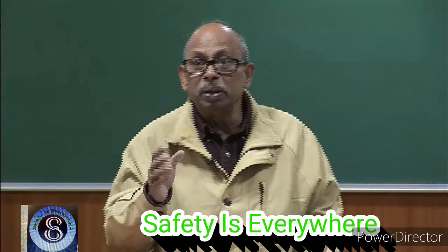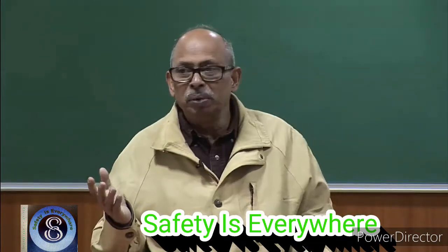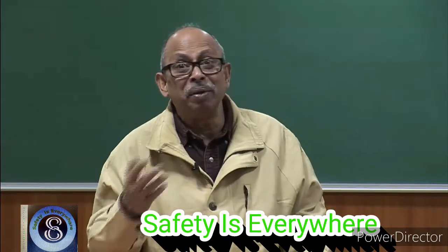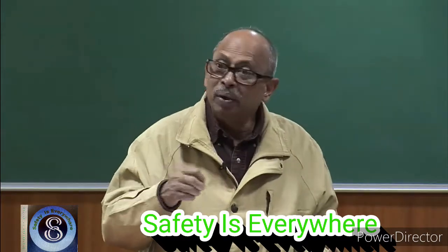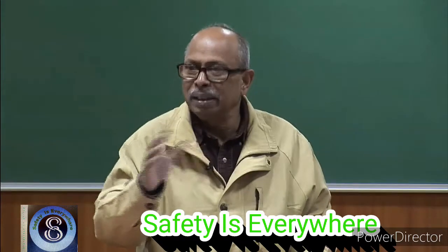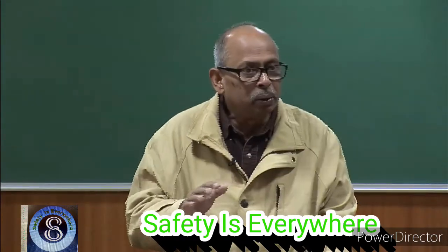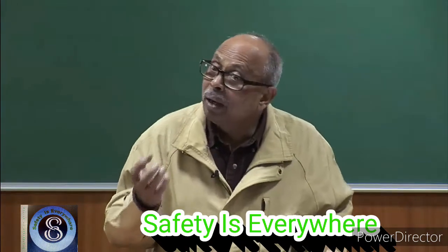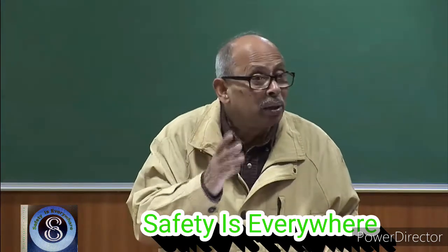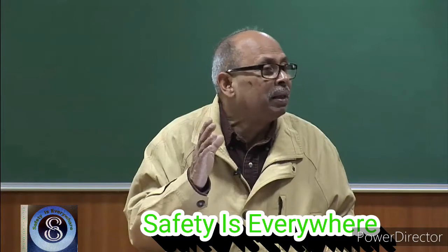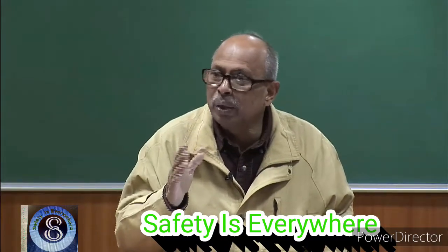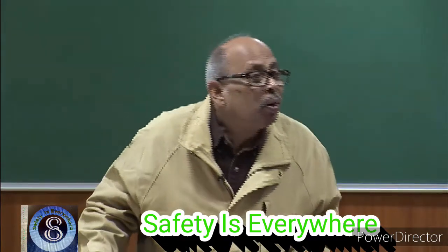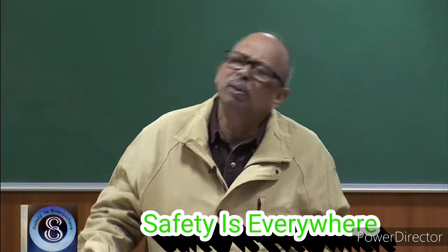Supposing somebody wants to change the furniture of a classroom tomorrow and it becomes lightweight, the load actually changes, or it becomes heavy because you have put in some teaching equipment. Number of people come and go. So, it is very difficult to come out from measurements with a 5% load, that the characteristic load is exceeded only 5% of the time. So, people have arrived at that by consensus, experts' consensus all over the world.